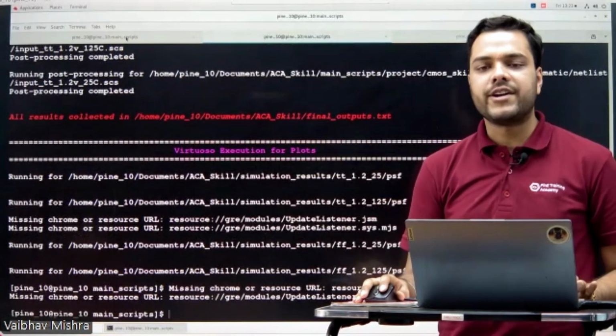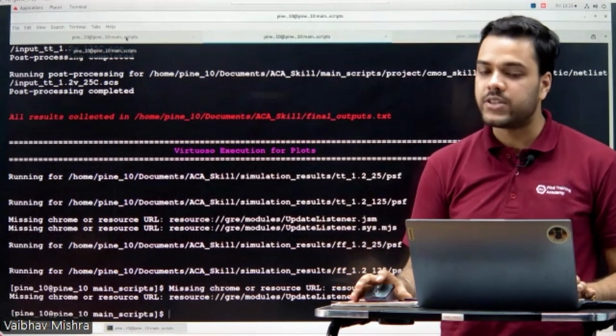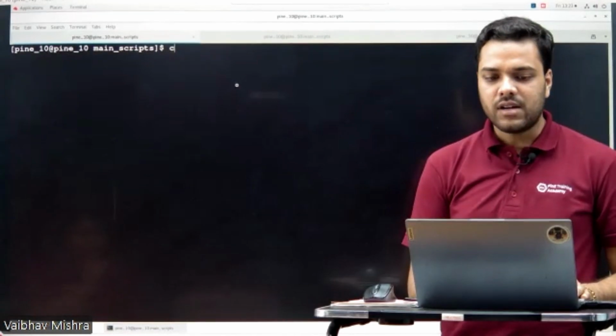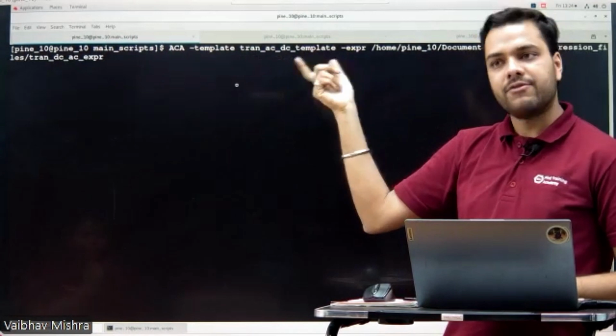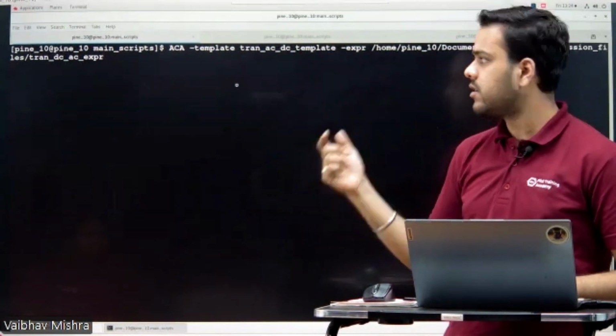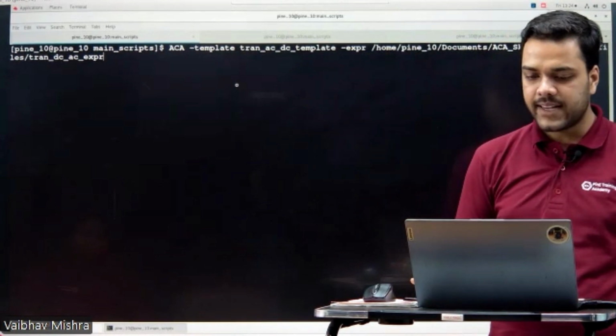You might all be wondering if we can run DC, transient and AC analysis at the same time. Yes, you can. Now let's check the same. Now I'll be giving the template file as tran ACDC. I have named this template file for my easiness. You can update the name as per your needs. Same with the expression file. I have given the expression file path and now pressing enter.